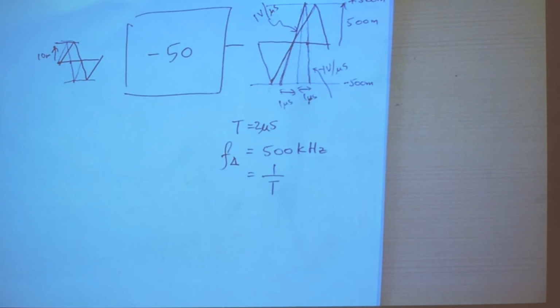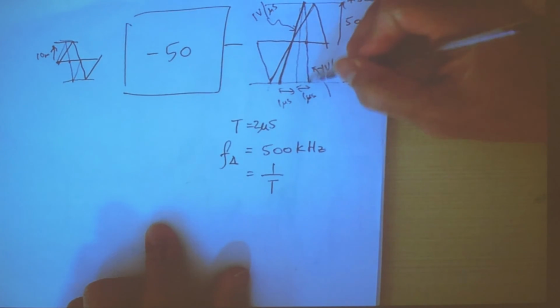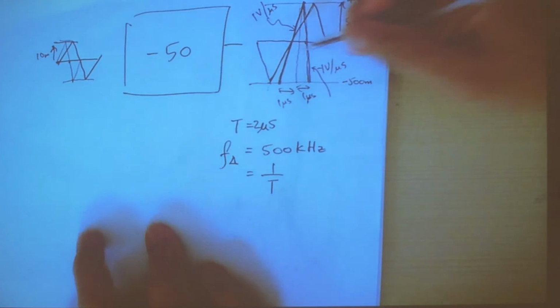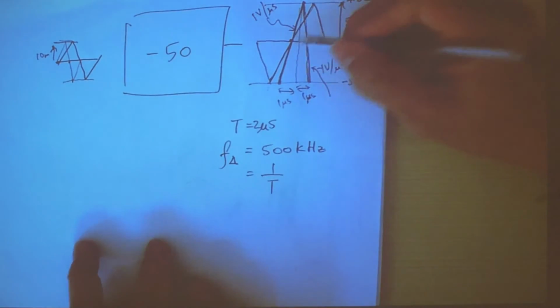Anything higher than that, what happens? What happens when the frequency increases beyond 500 K? The output will not be able to follow the gain of this amplification. In other words, the slope will always be this slope. So as I increase in frequency, the output zero crossings must come closer and closer to one another, right? Correct? So therefore, what would happen?